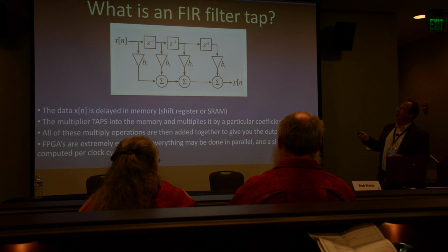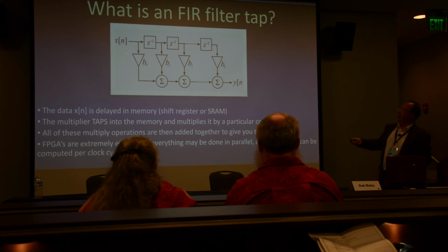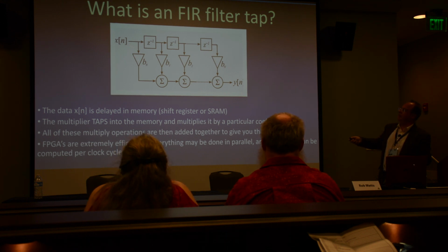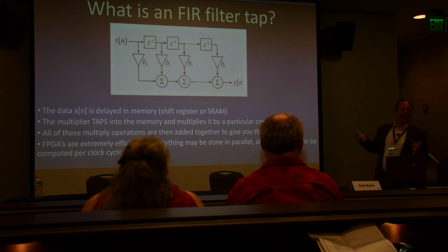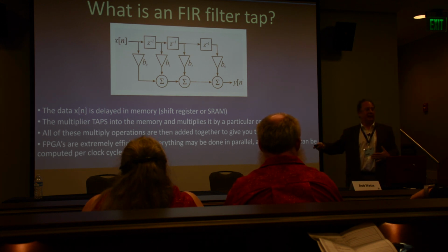But what we have is the data coming in here, and then we store it in the register, and it gets delayed, and delayed, and delayed. And then there's a coefficient here that is multiplied by the data, so this is actually a multiplier. But the key idea of taps is that the multiplier taps into the delay line, and that's why the term taps has been created, because you're tapping into the data.